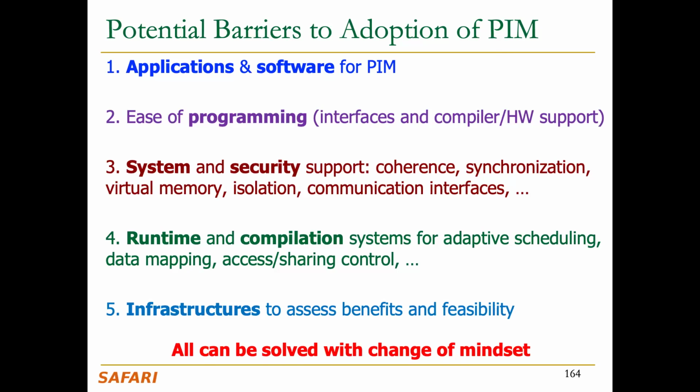Hi. So I see that some earlier PIM models, like SRAM PIM or processors using memory, are kind of small scale, in edge scenarios. And you just mentioned that in DRAM, you can only do 3-row activations. And it seems that it's already bottlenecked by the variation and signal-to-noise margin. Do you think it can be made to work at a larger scale, like server scale or supercomputing scale?